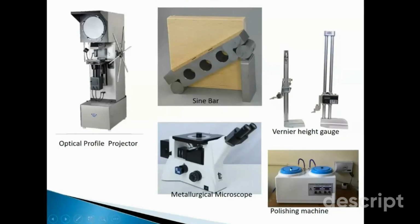Then we have another apparatus called a double disc polishing machine. It has two rotating tables, and currently this is covered with two flaps. Beneath it there is a rotating table, and there is an arrangement, or you can say a fixture, to affix the sandpapers, emery papers, which you all know are used to smoothen and grind the surface. Both these tables rotate at predefined velocity using these knobs.